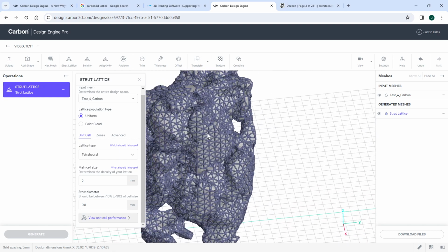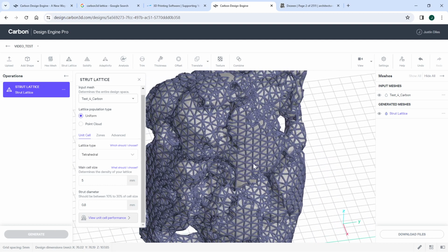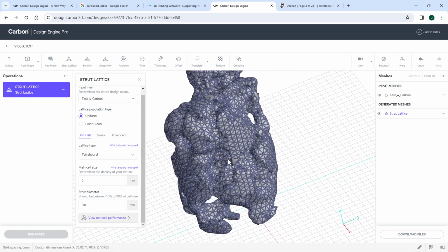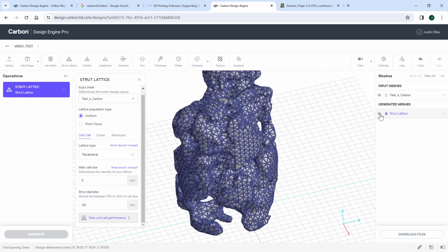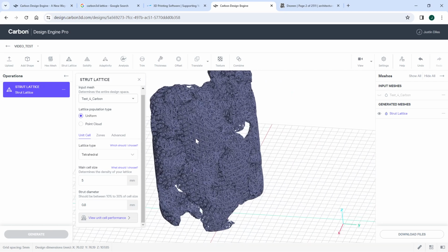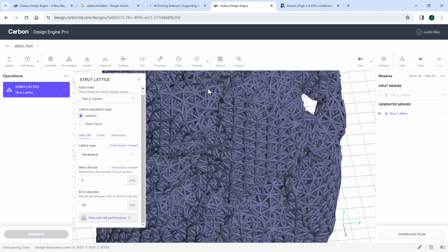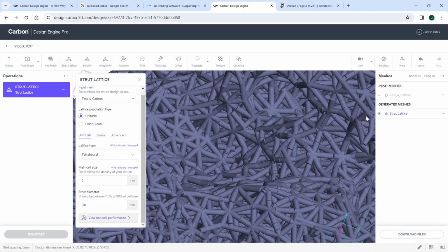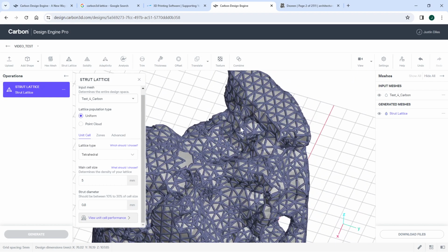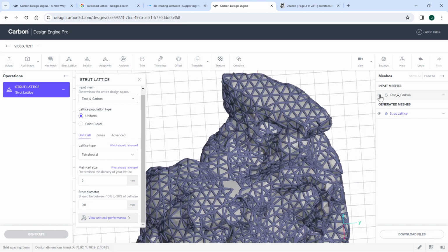After touting how cool it is that you can get these boundary surfaces or struts along the boundary, it should run faster if you turn off that feature, and you can also get really interesting results with that feature turned off. So I'm going to turn off the base surface, and now you can see this incredibly dense lattice following the shape. And again, I think the really powerful feature of this, which not all latticing tools have, is the ability to read the surface with the lattice itself.